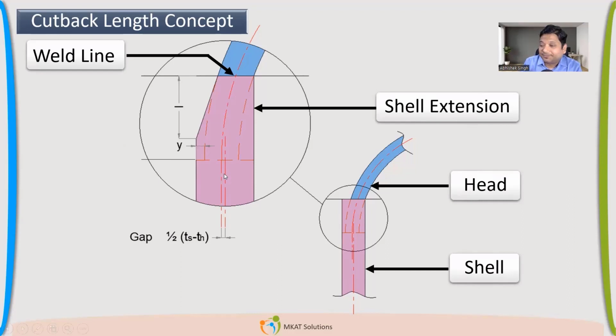Now it's tapered, and the taper is now located within the addition. This is the tan to tan line. It's located here. So now from here your straight portion is starting, and you will not have any problem in the thickness of the cylinder. Whatever thickness we are getting, it's the addition, and we are having more than the required thickness.